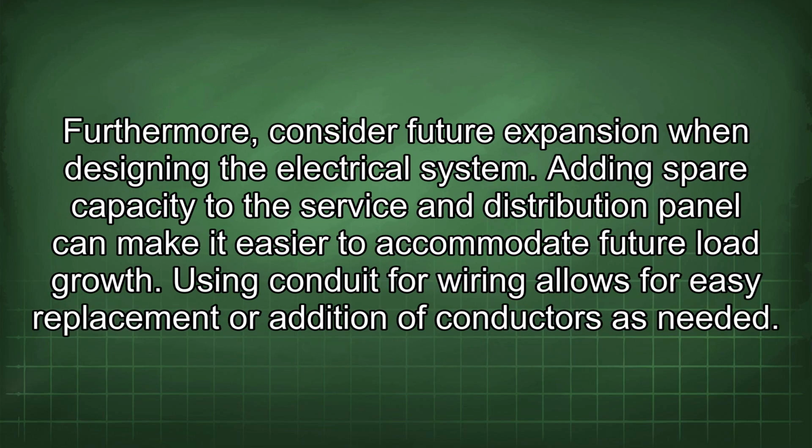Furthermore, consider future expansion when designing the electrical system. Adding spare capacity to the service and distribution panel can make it easier to accommodate future load growth. Using conduit for wiring allows for easy replacement or addition of conductors as needed.